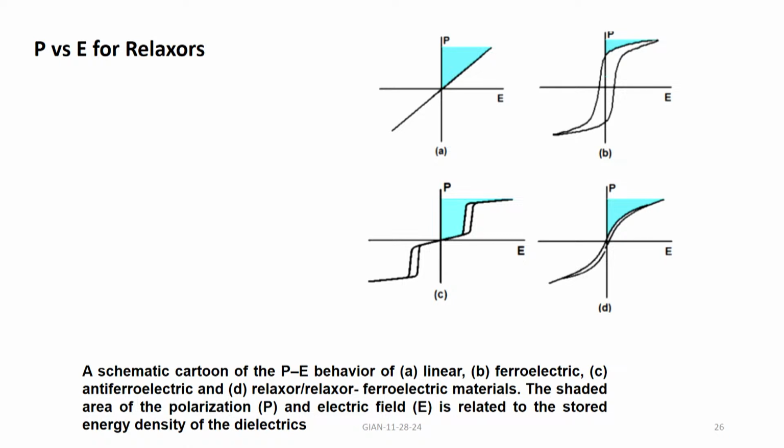The third one is what's called antiferroelectric. So the polarization vectors are antiparallel to each other, and you don't have to worry much about it. We don't come across this. Lead zirconate is antiferroelectric, for example. And finally, relaxor ferroelectric is characterized by a thin P versus E, whereas this one is spread out, and the remnant polarization is rather small compared to